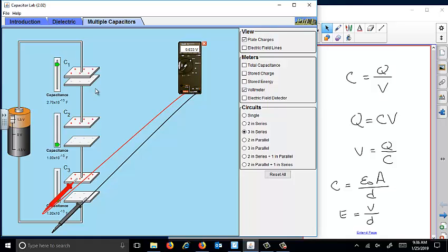It's because what has to be common between all three of these is not the voltage. What has to be the same is the amount of charge, because any charge that I get here I have to steal from there. So the charge has to be distributed equally between the three capacitors when they're in series. And if the charge is the same but the capacitance is higher, then the voltage for the higher capacitance capacitor is going to be smaller. So that's why we're seeing this kind of behavior.